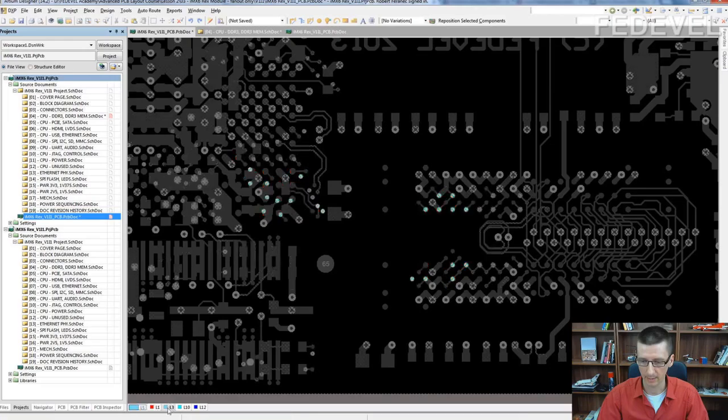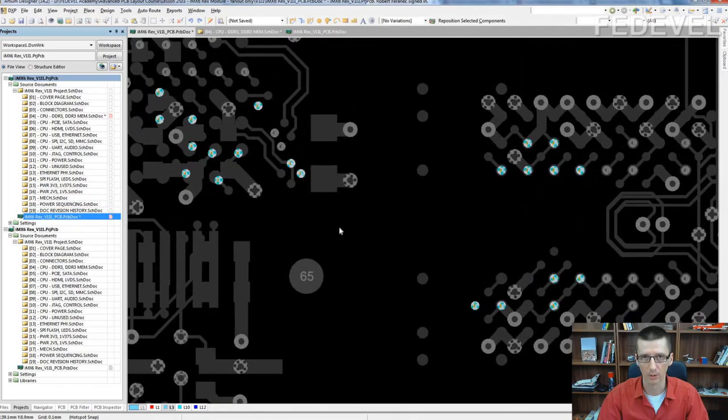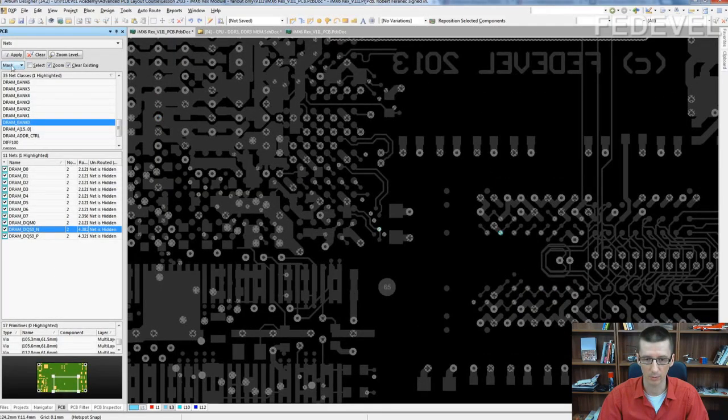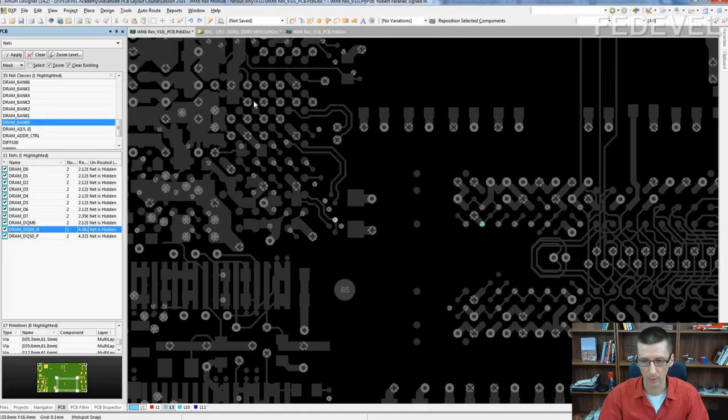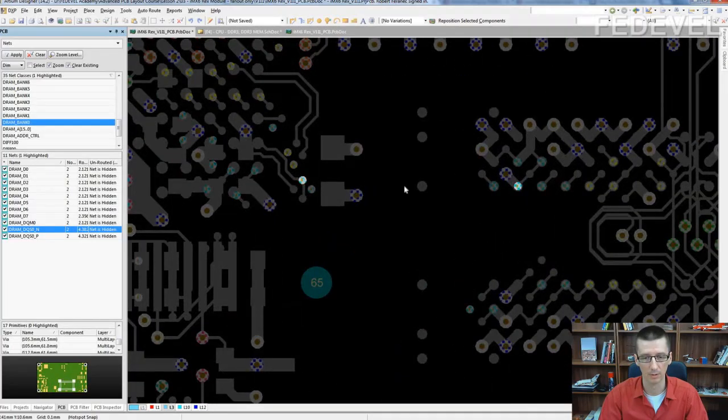I go on layer 3 and we will start the layout with the signals which cannot be swapped. So DQS, for example. And I will use dim. Do you know what's the difference between mask and dim? If you use mask, you cannot work with these other signals. If you use dim, you can work with these other things. See? So for the layout, I will use the dim mode.